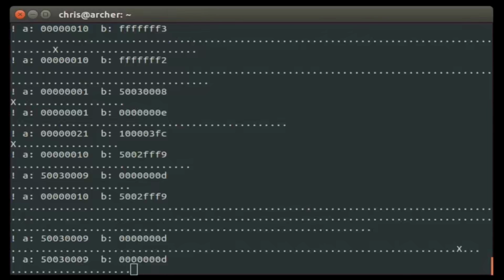But we have a variety of different effects. The main point here is just that we're having some effect on the chip. The code isn't operating normally. All that I'm doing at this point is dropping the VDD supply to the chip very briefly during that loop. By doing this kind of a test, I have a nice area to target where I can tune things in and find what length of glitch and what voltage levels will most likely have a good effect on the chip.